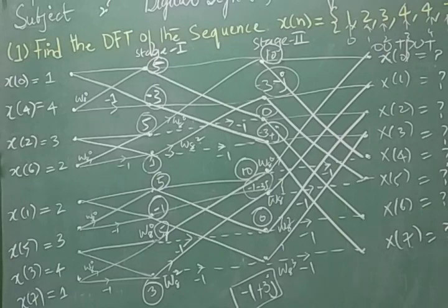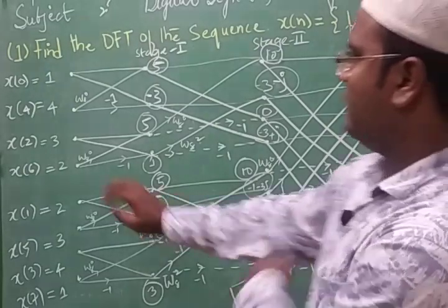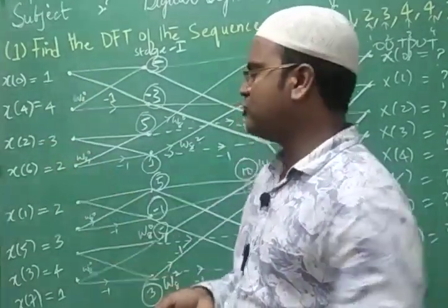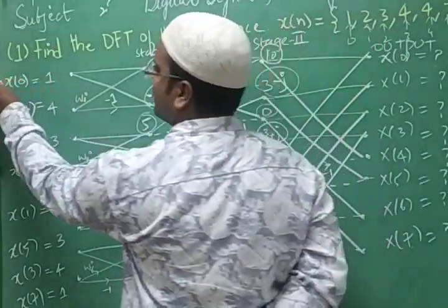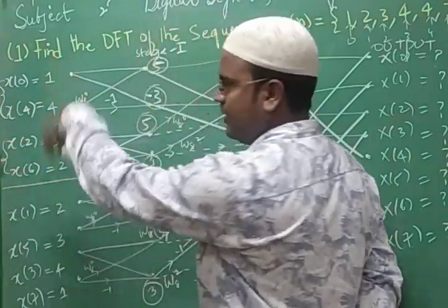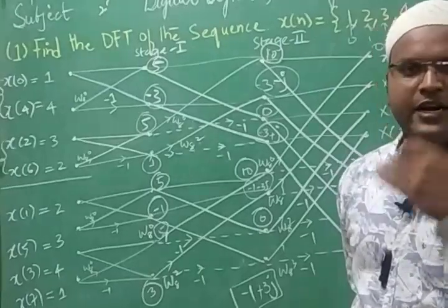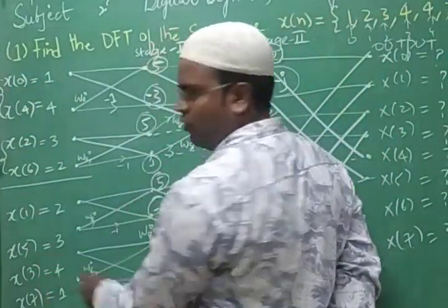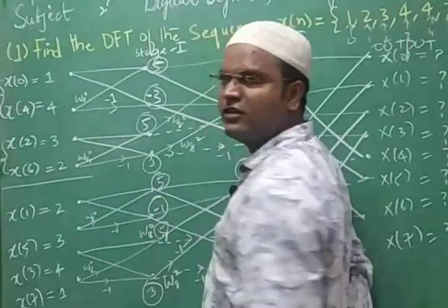That realization, how do we do it? You see what we have done. We have taken all these input values, right? 0, 4, then 2, 6. The difference of these two is 4, taking the inputs is very important. This input difference is 4, this input difference is 4. This is even. Decimation, half, segregating into two parts. The upper 2 are even inputs, then the lower 2 are odd inputs. That is nothing but bit reverse order.